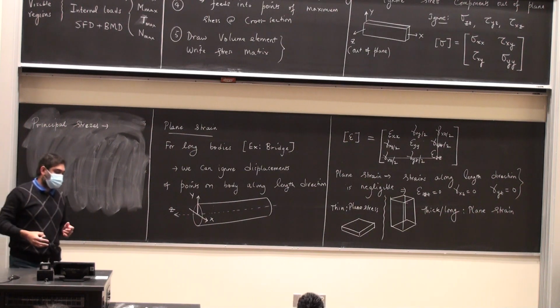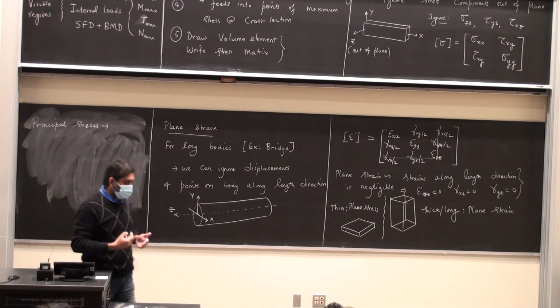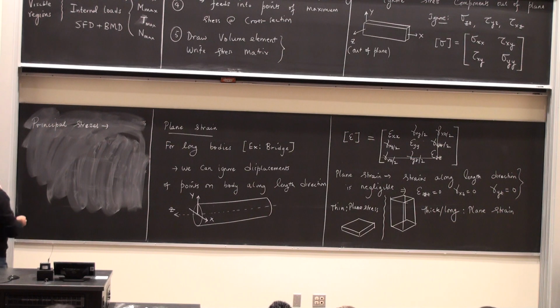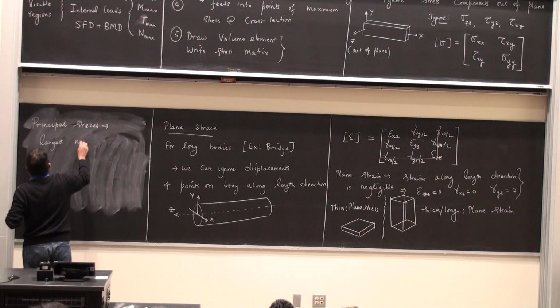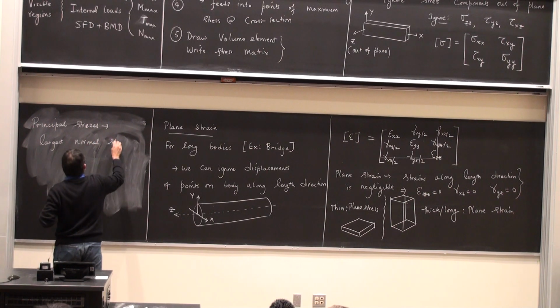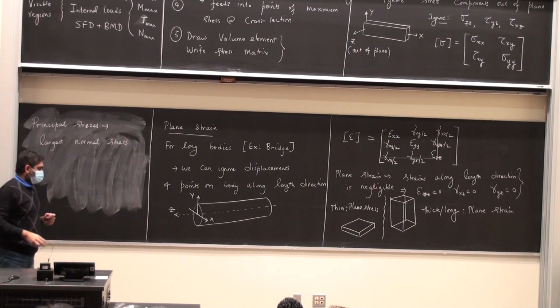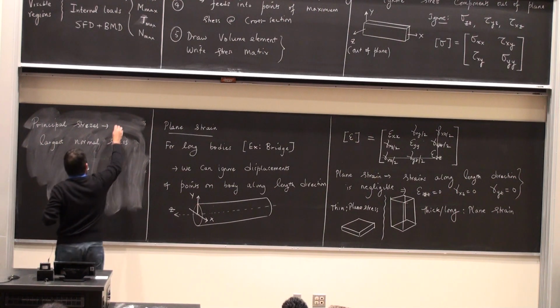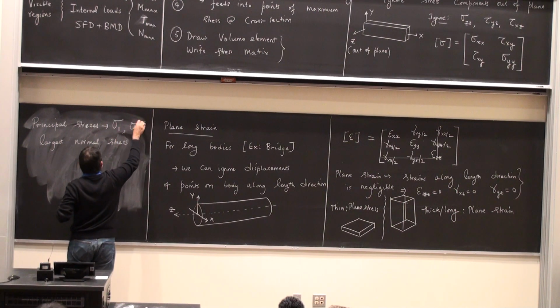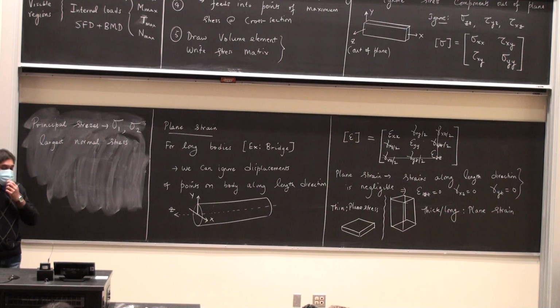Right, these are stresses that are the largest normal stress values. Okay, so the largest. And we are going to limit ourselves to two-dimensional problems, right? Plane stress situation. In the plane stress situation, I'm going to have only two principal stresses, sigma 1 and sigma 2, right? They're going to be called sigma 1 and sigma 2. The planes that contain the principal stresses are free of shear.